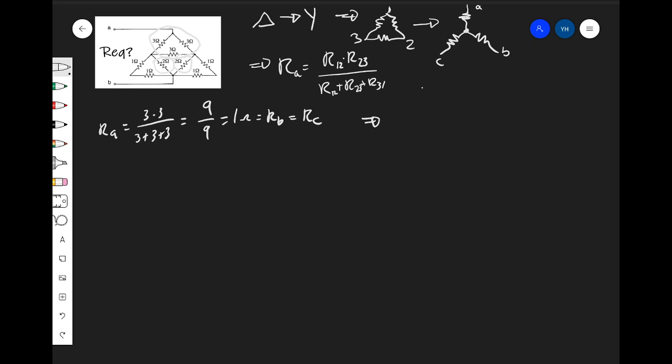If we redraw the circuit starting from A, we can go down, draw our first RA resistor, and then we can draw our RB and RC. Now if we look where they connect at the nodes, there's a node here that will share two more resistors, the 2 ohm resistor and the other 2 ohm resistor, which will combine at the end here, and they also will have the 1 ohm resistor and the other 1 ohm resistor as well as here, and we go back to B.